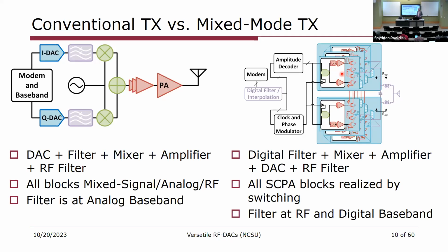So we're going to drive these signals at logic levels into the capacitor. And our digital to analog conversion happens by having banks of these essentially 1-bit mixers that are paralleled together that we can enable to increase the output power. And finally, we have some additional filtering that can be brought to bear using an RF matching network that also is small compared to an analog baseband filter because the frequency is typically significantly higher.